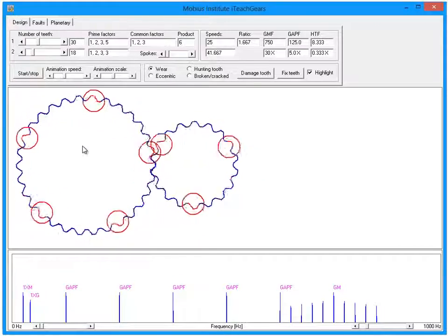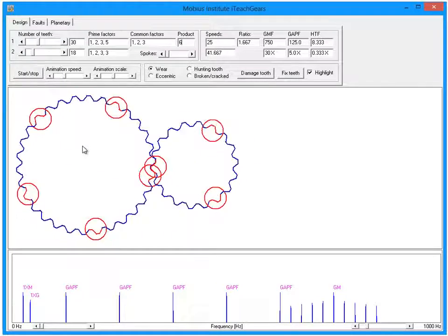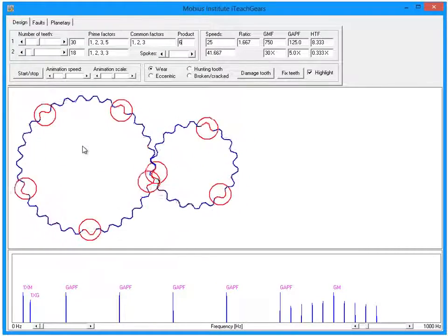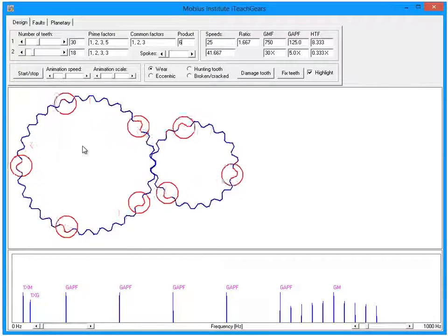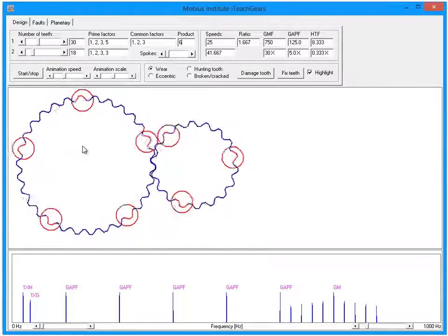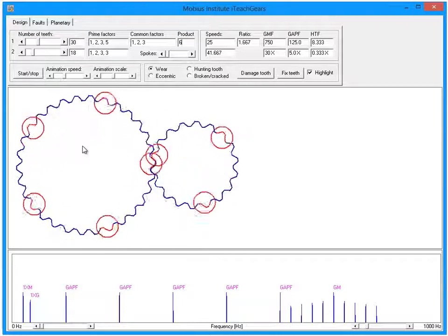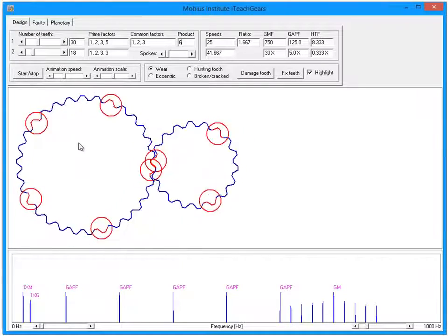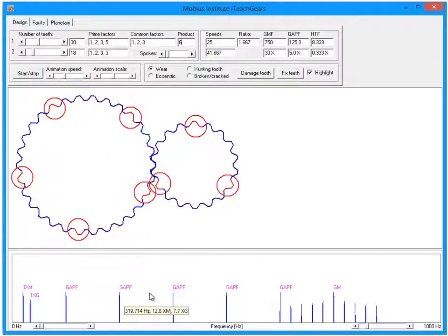Now, when it's in the gearbox, even though it's mating with the other gears, it's on a shaft which is supported by bearings and so on, it still has a natural frequency. It may be different because the stiffness is changed and so on because of the configuration, but it still has a natural frequency, and therefore we have the potential to see additional peaks in the spectrum related to that natural frequency.